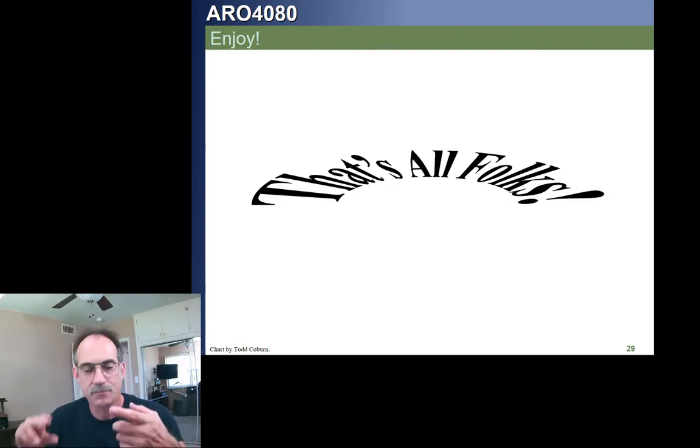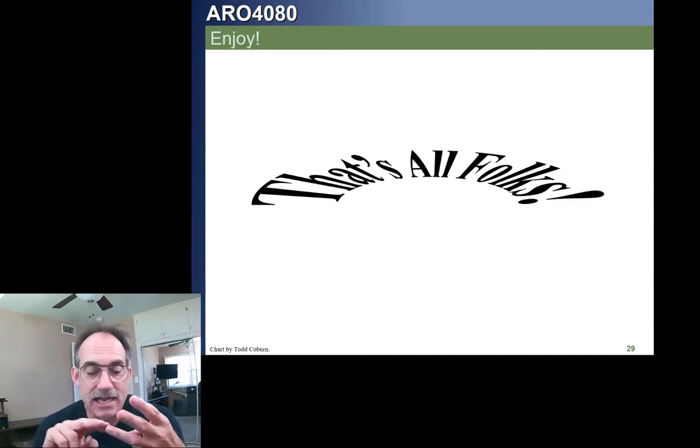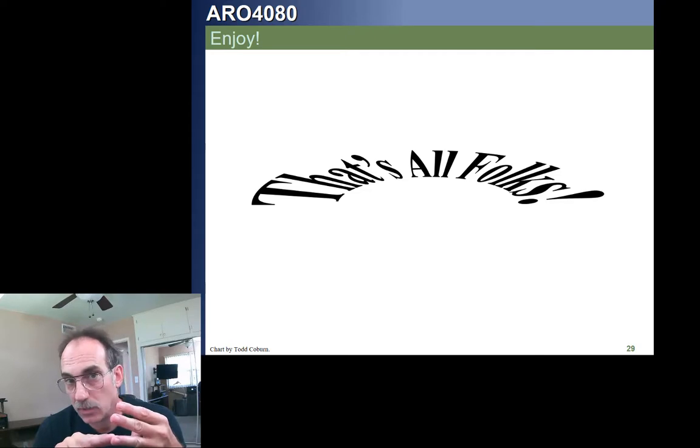Okay, so once again, we're going to be able to calculate the local stiffness matrix for any element. We're talking springs that are aligned in the global coordinate system. You can assemble the global stiffness matrix. You can identify your constraints and which ones are 0 or which ones are enforced.